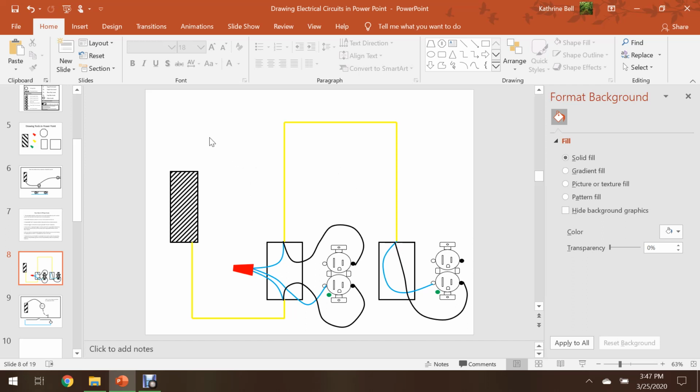The last thing we need to do is we need to ground everything. In wiring that we teach in agricultural education, typically we're talking about surface-mounted metal boxes. The National Electrical Code refers to these as normally non-current carrying enclosures. So any box that is metal that contains electrical conductors or devices would be a normally non-current carrying enclosure. As such, the code requires that we connect these boxes and devices to our service entrance panel grounding bus.